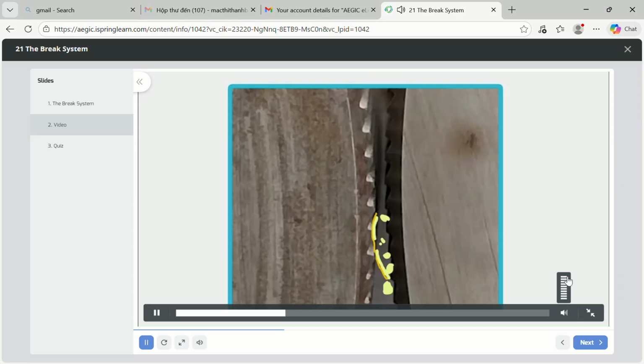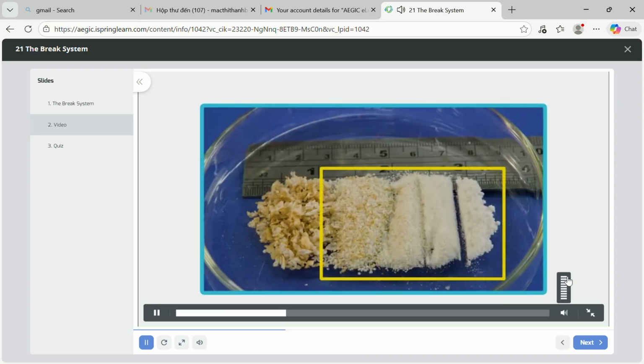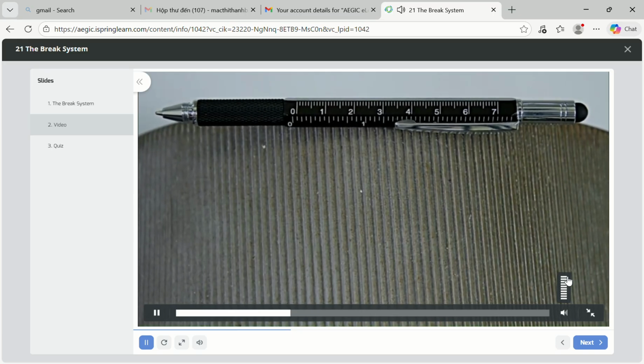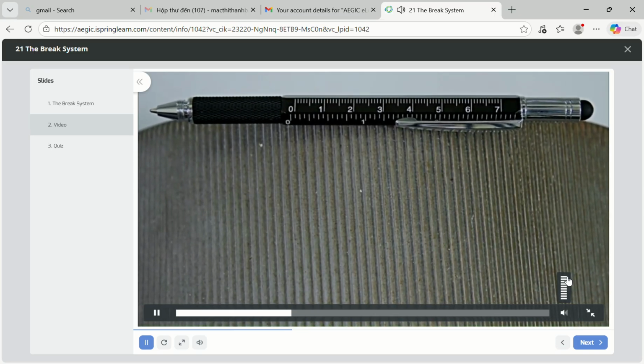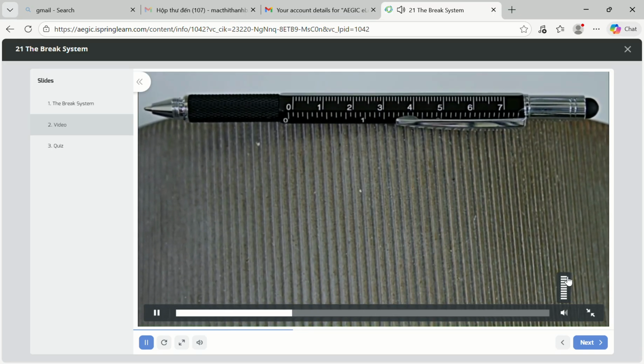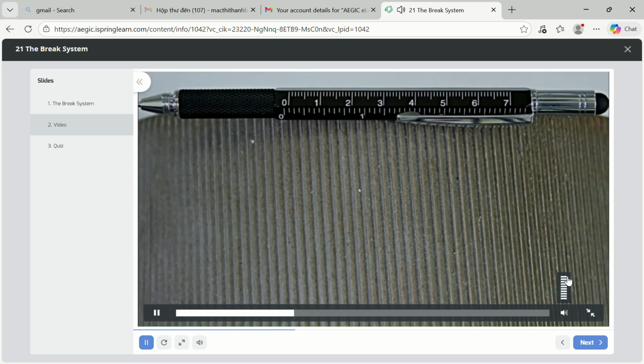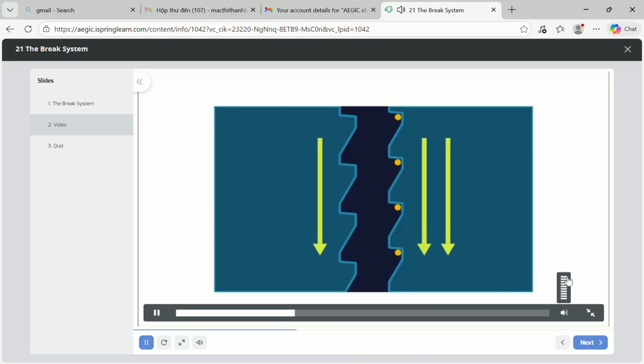As the faster roll continues to spin, the endosperm is scraped away from the bran in large chunks. First break rolls have relatively large flutes which help reduce over-grinding at this early stage in the milling process. They enable particles to hide between the flutes and escape over-grinding.